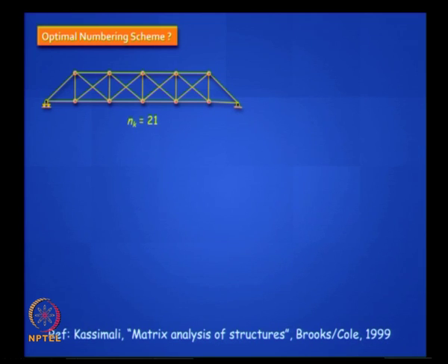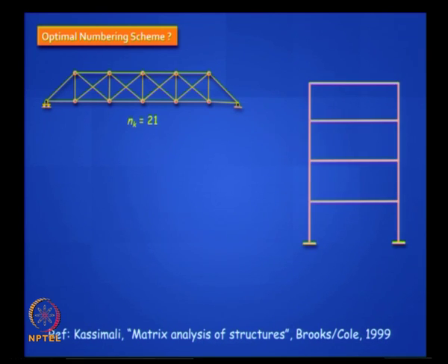So let us take a more difficult structure like a truss or a frame. Now you will find you have 21 active degrees of freedom in the truss and 24 here. We will figure it out later. Let us take the frame. Every joint has 3. Let us include axial deformation. How many free joints do you have? 8. 8 into 3, 24. Clear? Similarly for that truss.